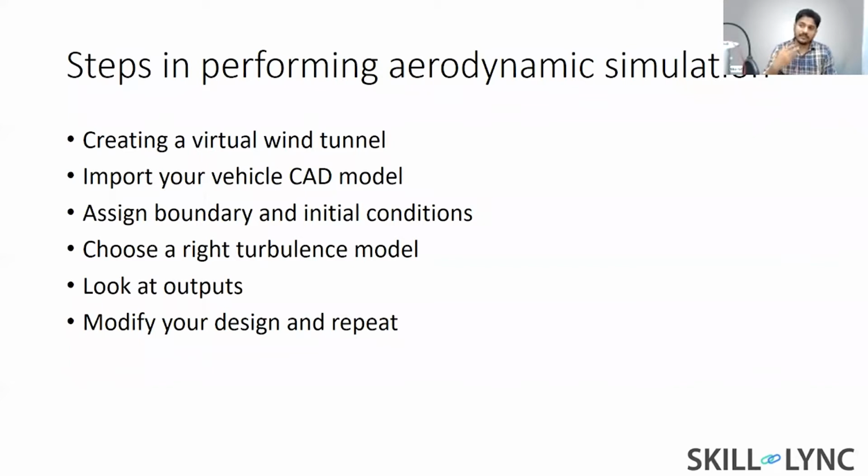So that is the process of testing, right? Even though you set up your CFD simulation perfectly, if you're just running one simulation and modifying the design, that's a huge mistake, because one particular design might do very well in one operating condition, whereas if you go to a different operating condition, it can completely fail. Okay, I hope that makes sense.